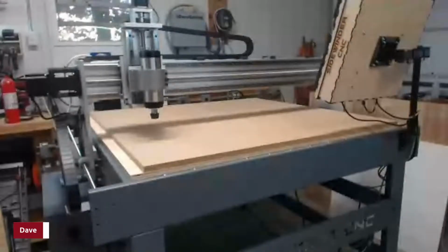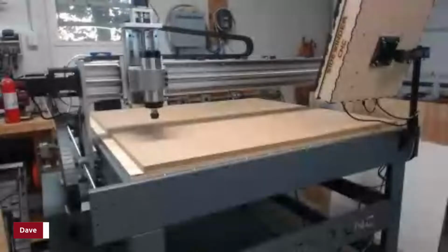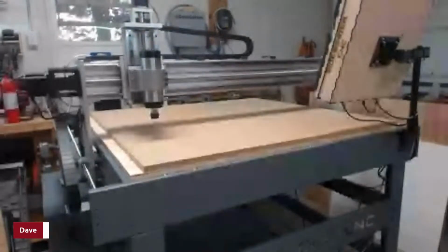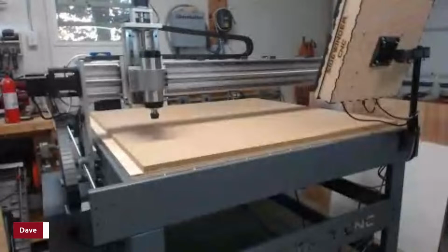I do have two drag chains on here, as you can see. And if you look there, that big one sticking out there, that's one of the NEMA 34s that's on the x-axis, and I had the other two NEMA 34s back there on the y-axis. And you can't quite see it with that camera shot, but the motor on top of the Z is one of the NEMA 23s. Like I said, I probably got 20 of those around here of different types.